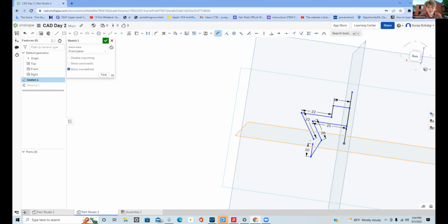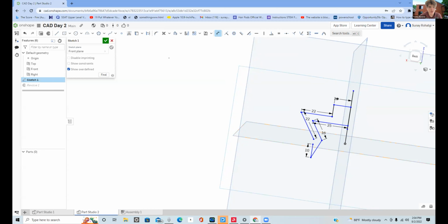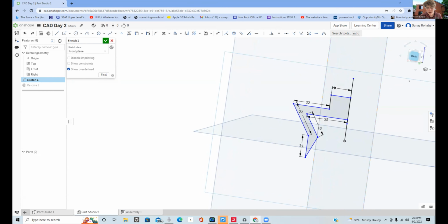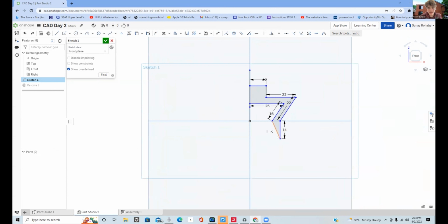Do you mind if I see how this works? Okay, so you're super close. Let's undo. So what you needed to do was just view. We want the distance between this point and this, which is the center, to be 10. The way to do that is to define it with the dimension tool. Take this, and then you click on this axis, and then you can see that now it's 22.3, which is why it's way too big.